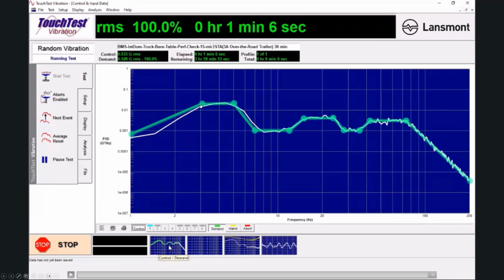It's going to have that average intensity, and it's doing the same thing for 4 hertz, for 5 hertz, 6, 7. It's sending out a random time domain signal that on average has content at each of these frequencies across this whole spectrum, with average intensity that is bounded or directed by the PSD profile, the green line. So the jaggedy white line that you see, that changes.